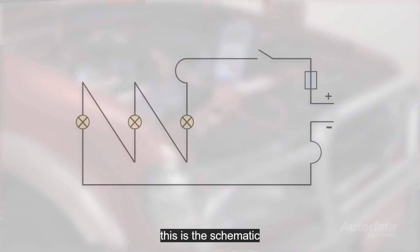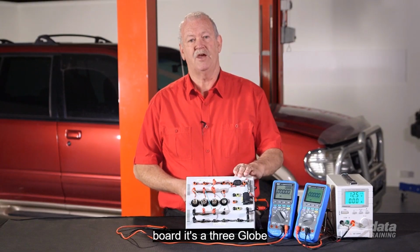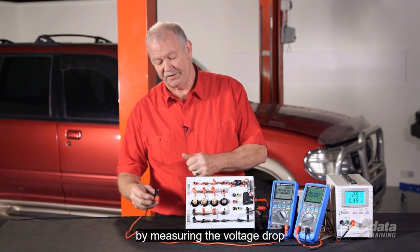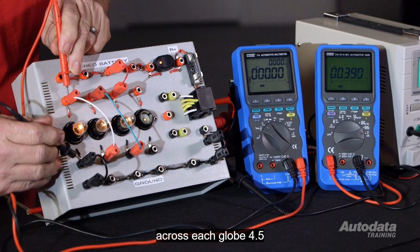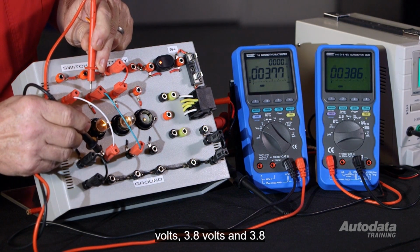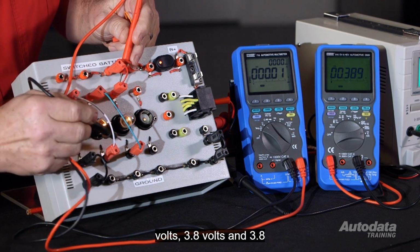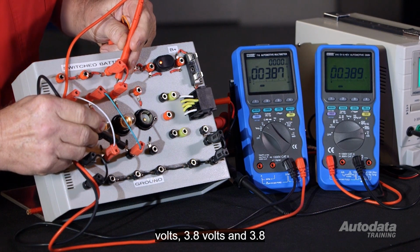This is the schematic of the circuit we'll be using on the test board. It's a 3-globe series circuit. I'll start by measuring the voltage drop across each globe. 3.5 volts, 3.8 volts, and 3.8 volts.